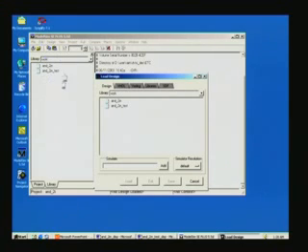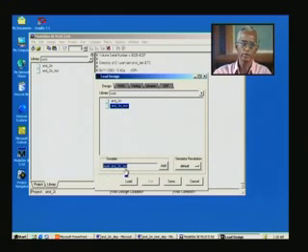these commands later on. And okay, now what we want is the test bench here, and you don't have to invoke this here because this is the topmost module. So if you double click, this will appear here, and this will be energized. This is a load button here. So I am just double clicking this. It says work.and2in_test. So this is the top level module that we have for the test bench, and it is in that work directory. So now you can load this file.